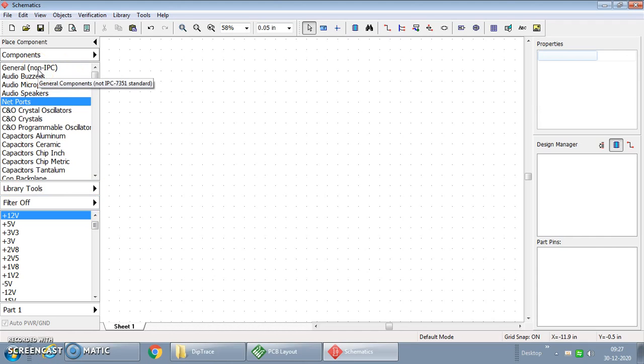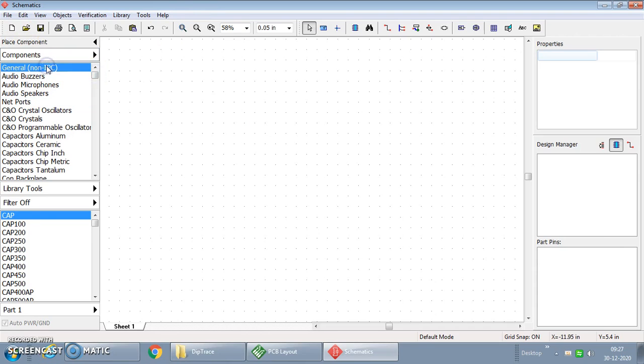Basically, the Astable Multivibrator to be designed using IC555 will use two resistors R1 and R2, one capacitor C, and one resistor at the output along with the light emitting diode. So the working of the Astable Multivibrator is wherein the LED is made on and off automatically by a delay which is set by the values of resistors R1, R2 and capacitor C. Starting with initial values of the components.